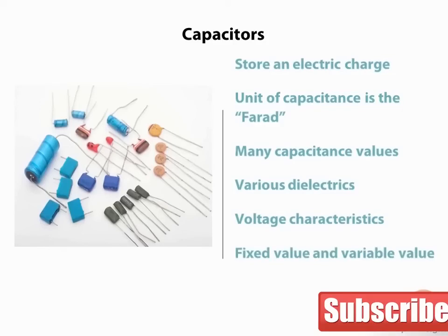We can find variable capacitors such as trim capacitors that can be adjusted with a screwdriver. Older vacuum tube radios have large tuning capacitors with air as the dielectric. These were adjusted to tune the frequency of the receiver. And some transducers will change capacitance proportional to the measured element. Many pressure transducers and touchscreens are capacitive devices. Condenser microphones are essentially a capacitor. Condenser is another word for capacitor.